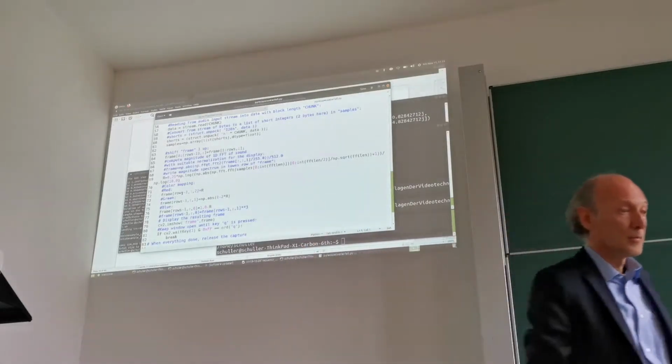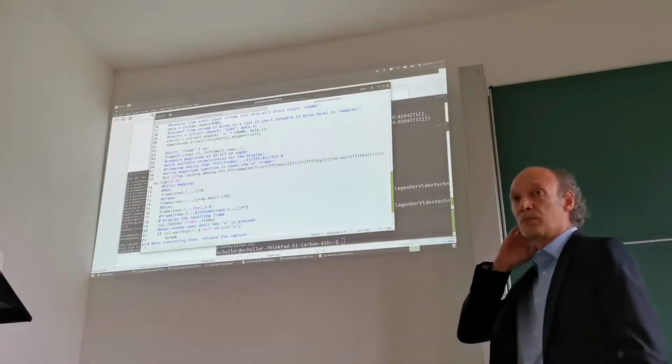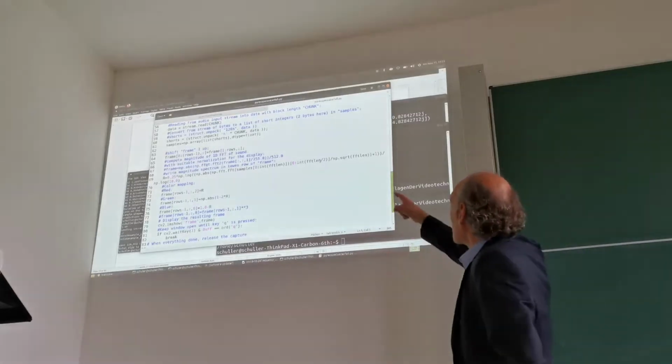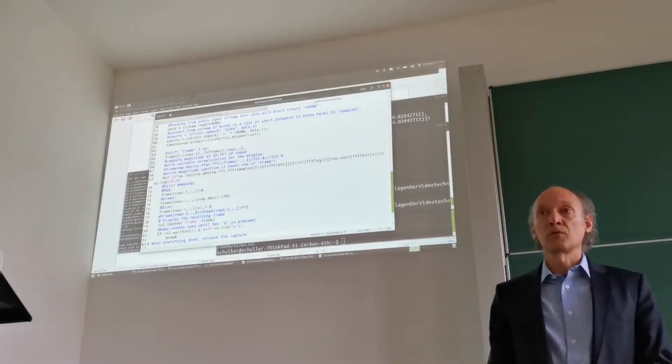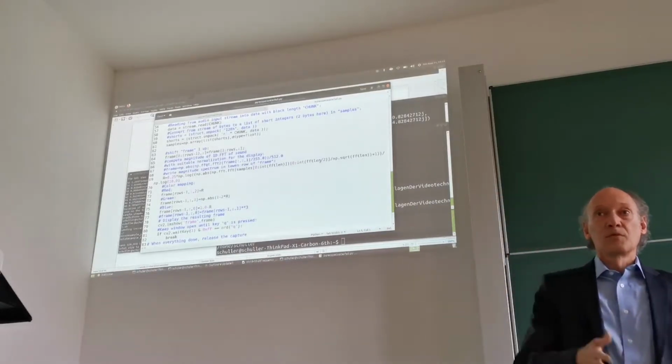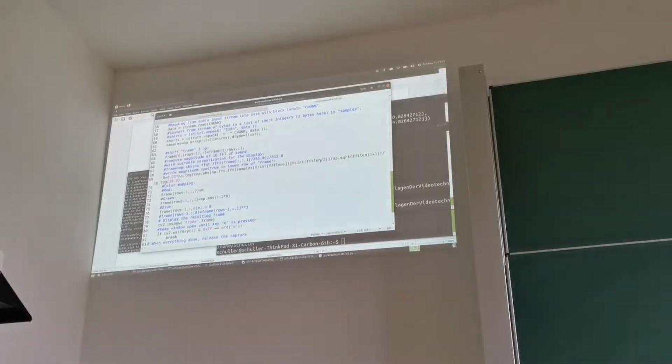Here I have the FFT length, but I'm only keeping the lower half, from 0 to FFT length over 2, and I'm typecasting to int to avoid an error message. Make sense? So I'm only going from 0 to Nyquist in this case.